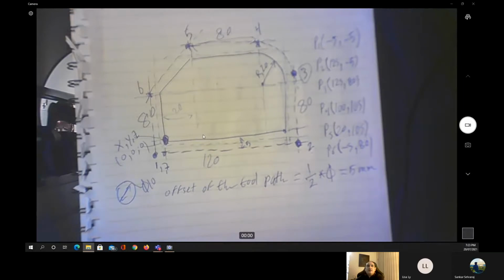Then you find the point coordinates and move the cutting tool center between them to the required depth in the case of 3 dimensions, and this will give you the proper code for the cutting tool to generate the required geometry.